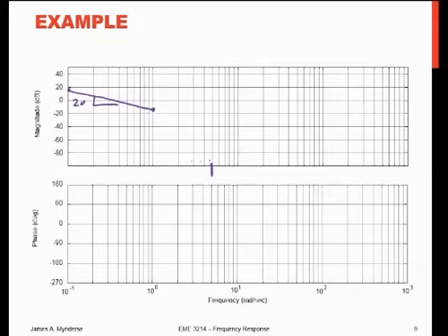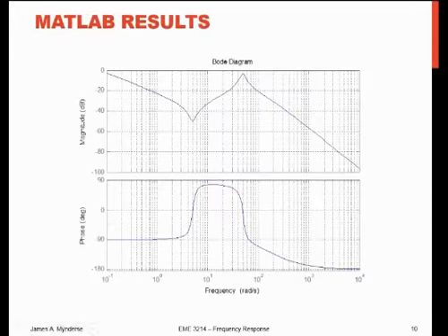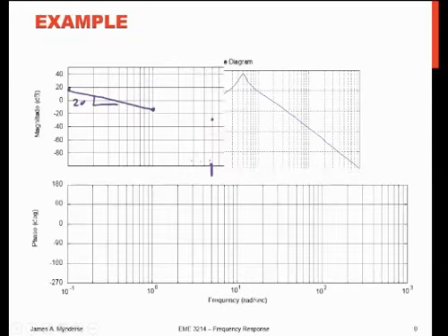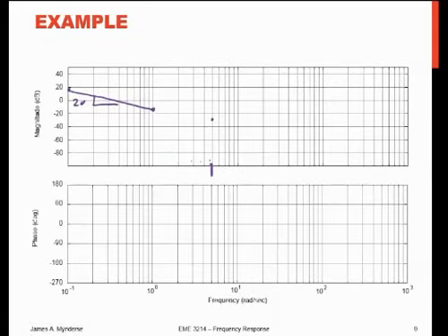It'll hit about here. Oh, sorry, I leaned on my screen in the wrong spot, trying to steady my hand. So that'll go there. When I get to this peak, now I'm adding a zero, so the zero has a slope of 20 dB per decade up. That cancels the slope of the 20 dB from the pole.